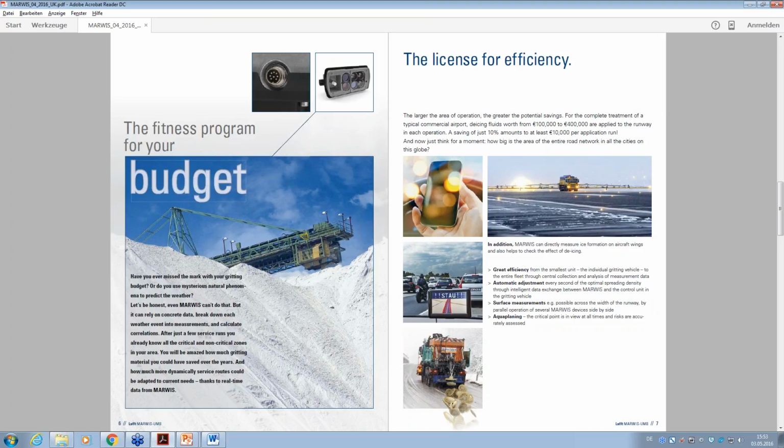So that is optimization. The other benefit is to do it proactively. So start the icing before it starts freezing. And freezing is not a 0-1 event. It is a slowly changing condition, where you can imagine a traffic light that is red, yellow, green. Green is friction is good. Red is definitely too late, but if friction is around 0.6, it starts freezing. It's still good enough to drive, but if you act now, you proactively act. If you start doing that at 0.5 or less, it's definitely too late.